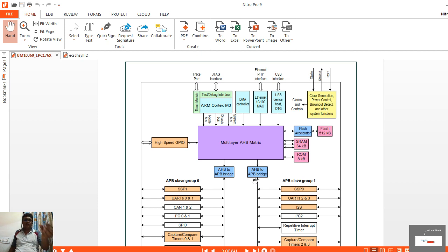They can decide the number of UARTs they are going to provide. It can be 1, 2, 4, etc. So it is going to be decided by the silicon providers. So these ARM people are going to provide only the processing unit. The rest is going to be decided by the silicon providers, and based on those applications, they can decide how many UARTs, how many CAN buses, how many DACs, or how many on-chip SPI peripherals, etc. You can see all these things in later videos, how these respective things get decided.